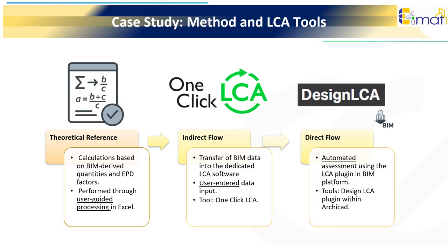For the case study, the authors applied the methodology and tools introduced throughout the course by comparing three complementary LCA workflows. The first is the theoretical reference, where impacts are calculated using BIM-derived quantities and EPD factors, processed through user-guided calculations in Excel. This manual approach provides a transparent baseline to validate the other methods.